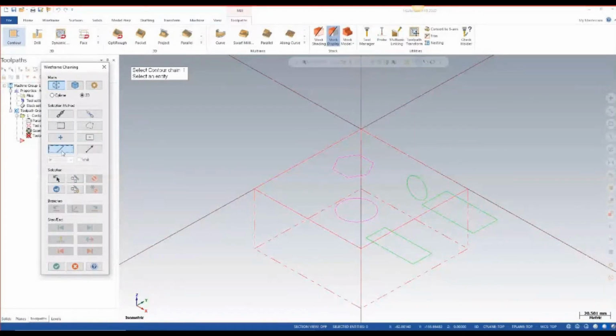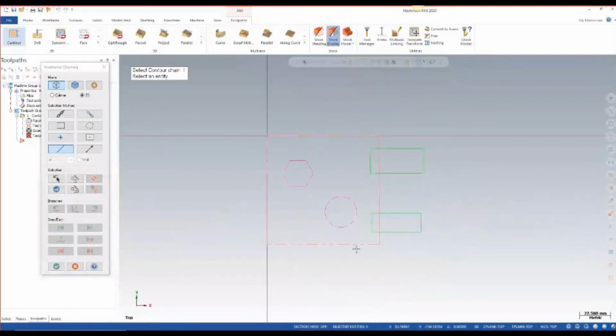So when you say single, let's say I want to machine this particular chain and this particular chain. In that case, I can't go with partial; I'd say apply, and go in this manner, which means I'm going to use 3 steps. Instead of that, I can use single chain. I'm going to define this chain and that chain, so only these 2 particular chains get selected and I can do my program.